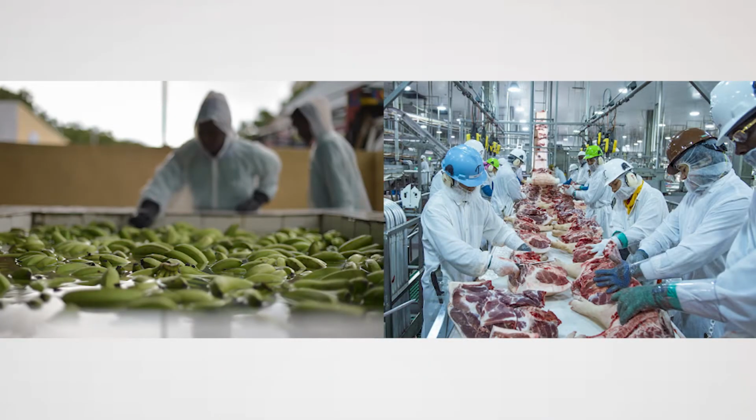Product loss, such as pieces of dough, chunks of meat, or cuttings of fruit that are washed away as wastewater, can be a large contributor to BOD levels in wastewater. In many cases, if these materials are separately captured, there is a secondary market for the material, ranging from cosmetics to animal feed. The wastewater contribution to the BOD varies for each material. For example, the BOD in effluent water from a system that processes cherries may only be around 100 pounds per ton, where the BOD in effluent water from a system that processes cheese may be near 1,000 pounds per ton.